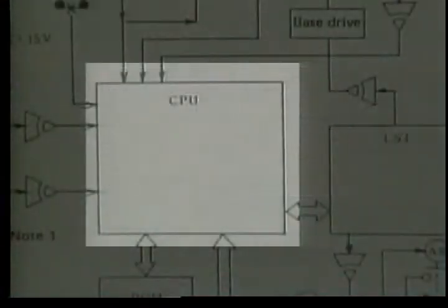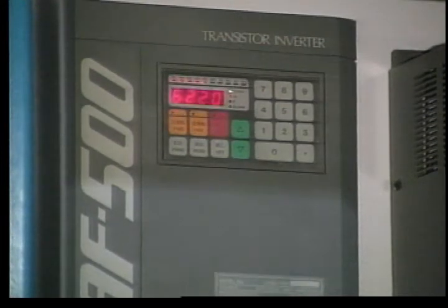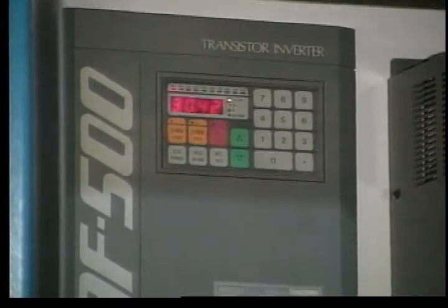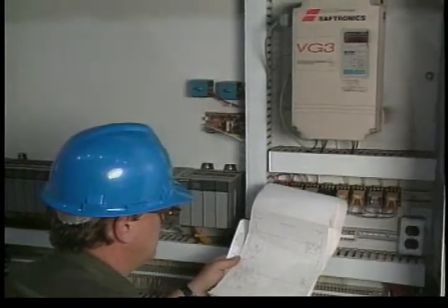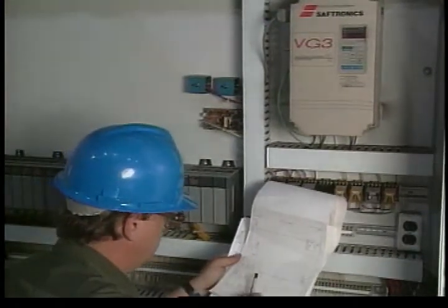The inverter's built-in microprocessor rapidly switches these transistors on and off in a particular sequence that generates pulses of rising and falling current. This pulsing current creates positive and negative magnetic fields that seem to revolve through the stator. By controlling when the transistors in the inverter section switch on and off, the microprocessor can vary both the frequency and the voltage the motor receives.